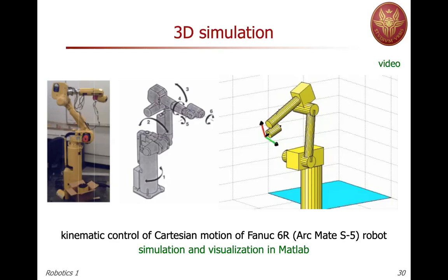In the previous simulation that we have seen, we said, okay, I have to go along this straight line with 2 meters per second. So the whole motion should be completed in, whatever, 1 second, 2 seconds. So we are assigning a motion and a desired timing law. If the error is 0, we will move exactly as we plan. If it's not 0, we have to compensate for the error in the initial transient, but eventually we will move there, so I will complete the motion. If not in the nominal, let's say, 1 second, I will complete it in 1.05 seconds and so on. But I will complete this in finite time.